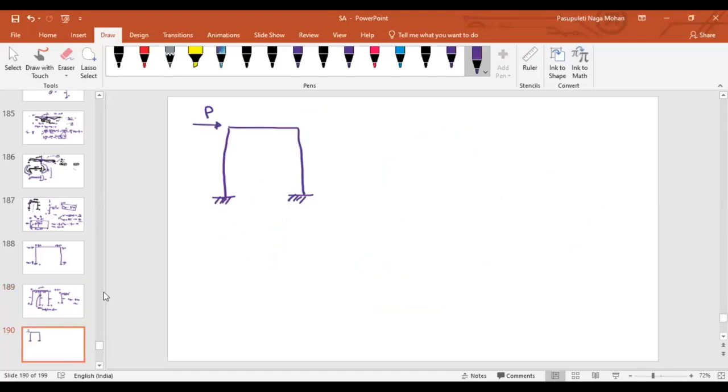However, in these types of cases, how do we have to approach here? What do you think the corrections will be in this case? Where is the difference that we have to consider? There will be a lateral deflection here, sir. Yeah, it is a sway case, right? Because of the load, the sway can occur. So whenever the sway can occur, I hope you guys remember it can be a lengthy process. And you cannot just directly obtain the moments as we have discussed earlier.